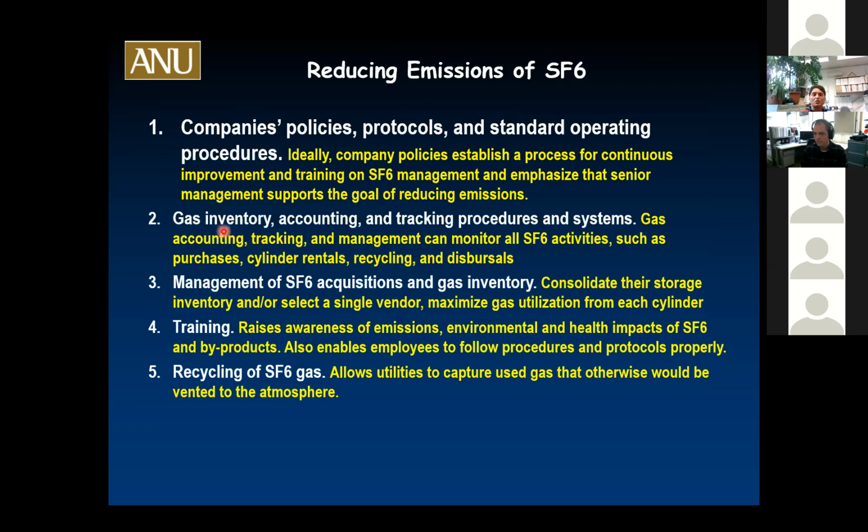It includes a gas inventory, counting, and tracking procedure system, so we can monitor all activities of SF6 like purchases, cylinder rentals, recycling, and disposals. So, management of SF6 acquisition and gas inventory: this consolidates storage inventory and selects a single vendor, or maybe maximizes gas utilization from each cylinder, like maybe pumping out the SF6 and refilling the backfill with other gases.